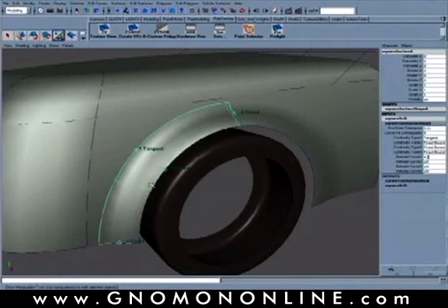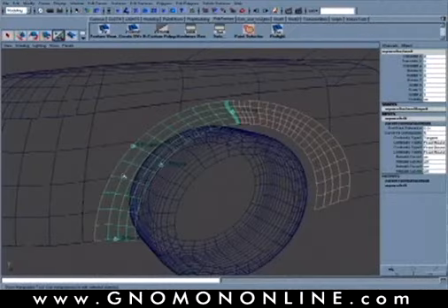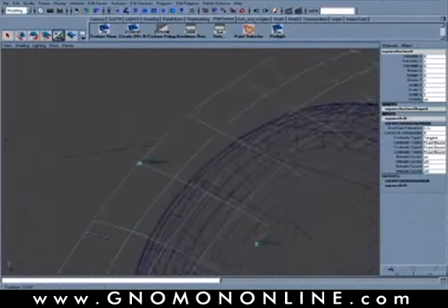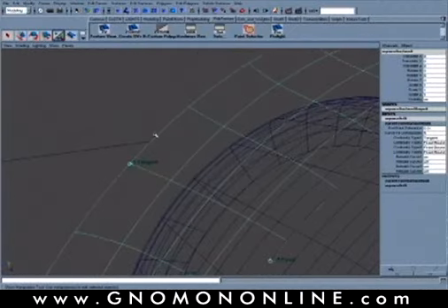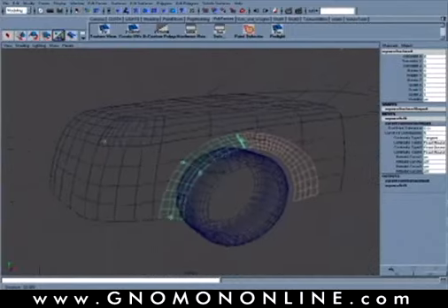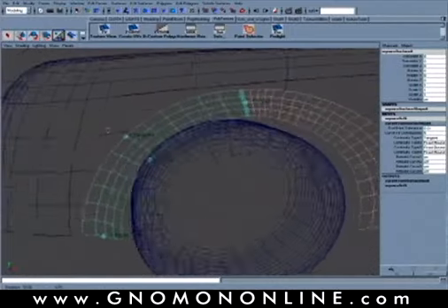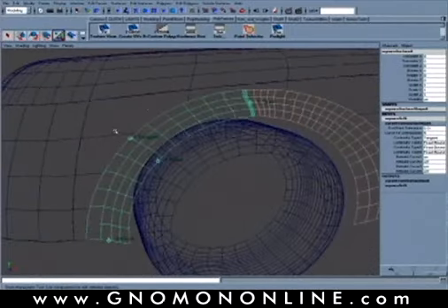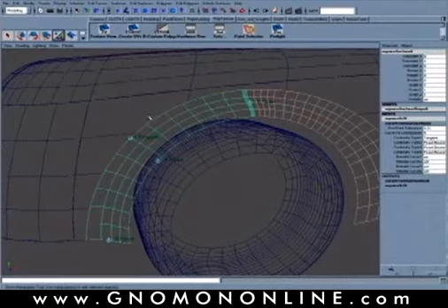Okay, you always want to check that in your real surface, meaning that where those two edges meet up, you want to check really close and make sure that it did not leave any kind of gap in the geometry, and that your tolerance is up large enough too to prevent any kind of gap in there.